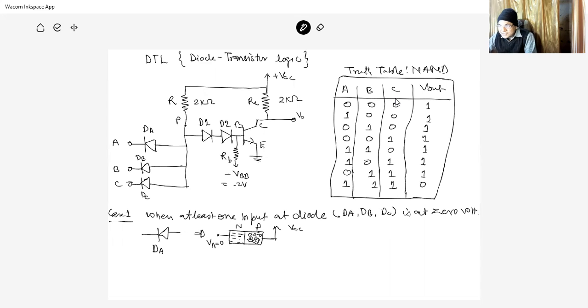In this case, this is positive, so the junction is forward biased, this 0 and this is positive. So electrons experience an attractive force towards the junction, and due to that the electrons cross the junction. So due to forward bias, the current is flowing across the junction. So what will be the potential?